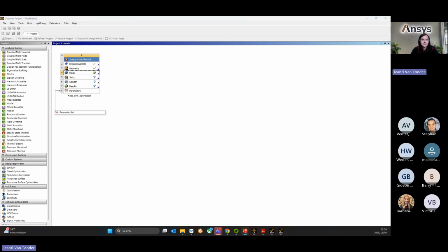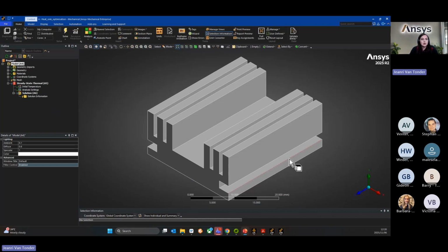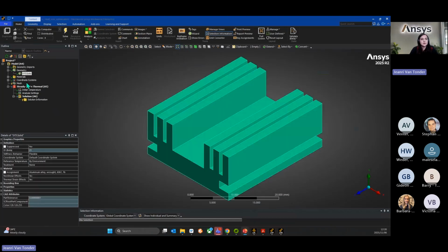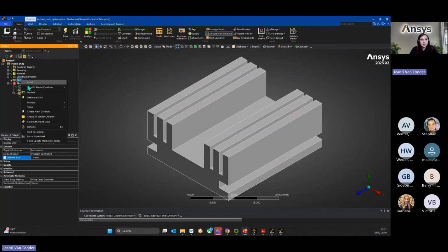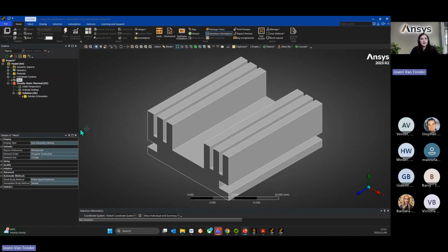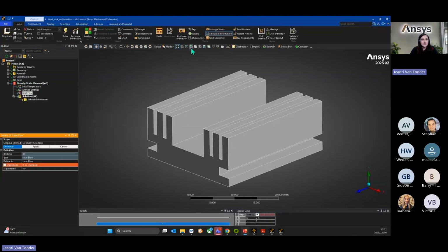All right, in Mechanical, literally just following your structure tree from top to bottom as usual. We'll assign our correct material to ensure the thermal characteristics are correct. Generate a very basic mesh. In this case, at least, the geometry allows for a really nice swept hexahedral mesh. Very important to keep your meshing parameters the same throughout your parametric study so that it doesn't influence the results.